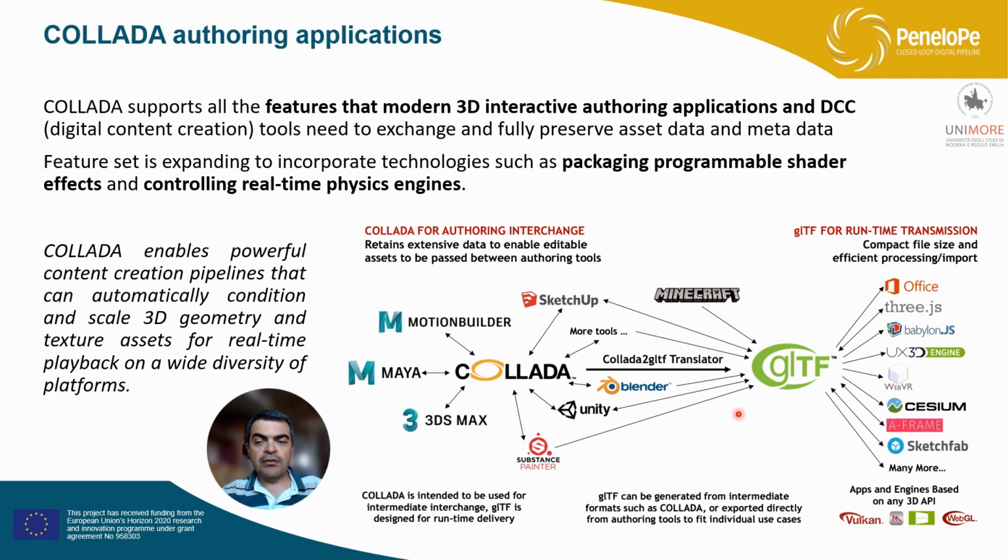To tell the truth, there is an emerging, quite new standard called glTF. TF stands for transmission format, so it's a graphics language transmission format. It's a new standard of the Khronos consortium, the same that defined Collada, which has more modern features. For instance, the file can be compressed, can be provided in binary format, and it gives the possibility of using the file for real-time applications. So it's a way of extending the capability of Collada also to more modern application environments.